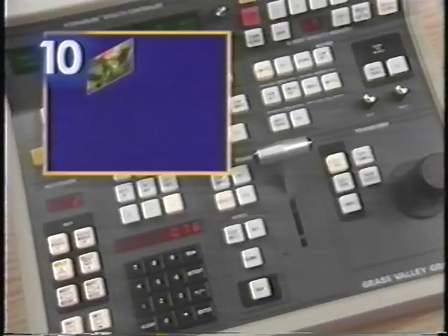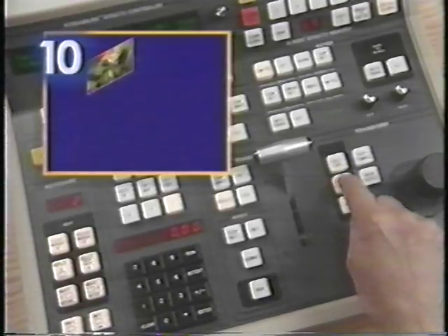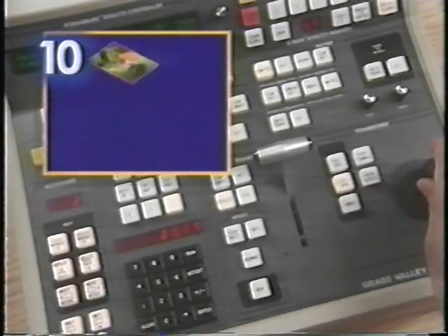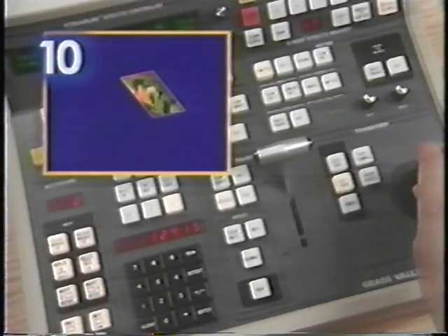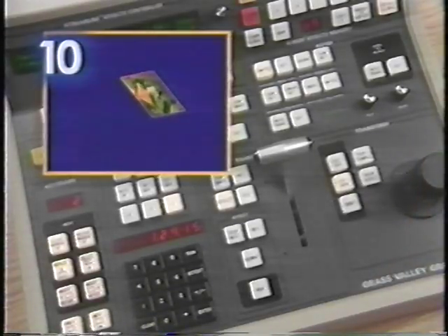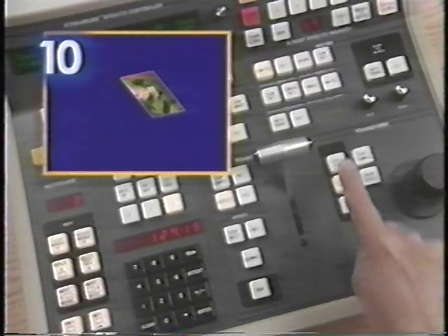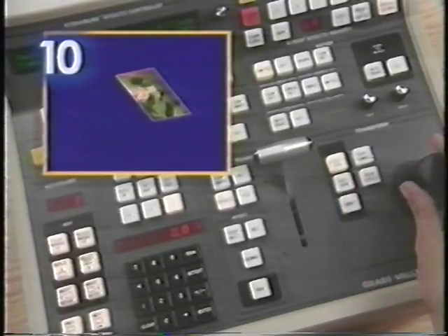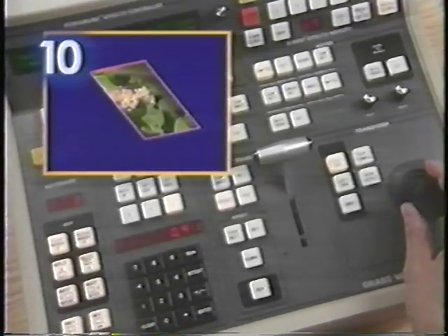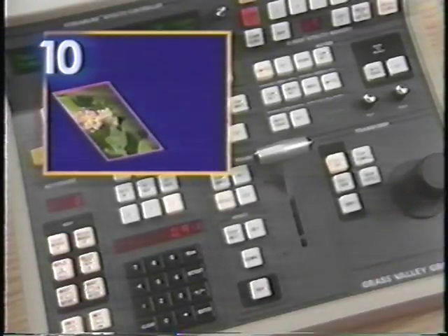For keyframe number 3, change the working keyframe by spinning the picture clockwise and relocating it using Locate Spin. Press Insert After to insert the working keyframe into the current effect space. For keyframe number 4, change the working keyframe by making the picture larger and relocating it. Use Locate Size and then press Insert After.